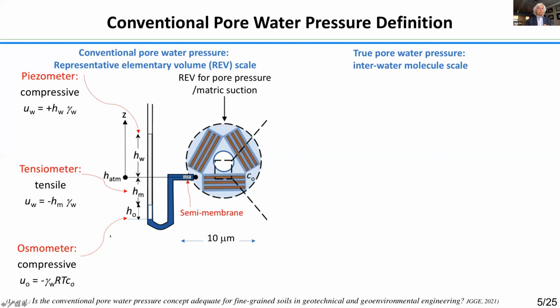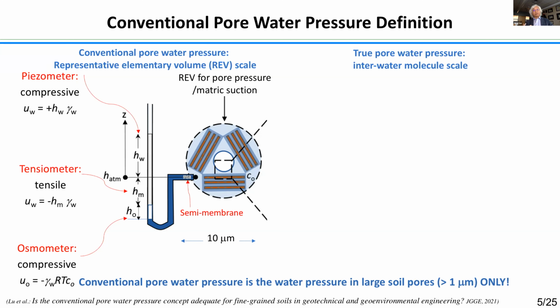That way we can establish a so-called osmotic suction, or sometimes called osmotic pressure, depending on which side you look at it. So here we can measure what the pressure will be due to osmotic suction, due to the concentration in your soil, because the fresh water is going to have a tendency to drag into that one under the equilibrium condition. So that is what we can currently do. With the current technology, most of the time we measure at millimeter scale.